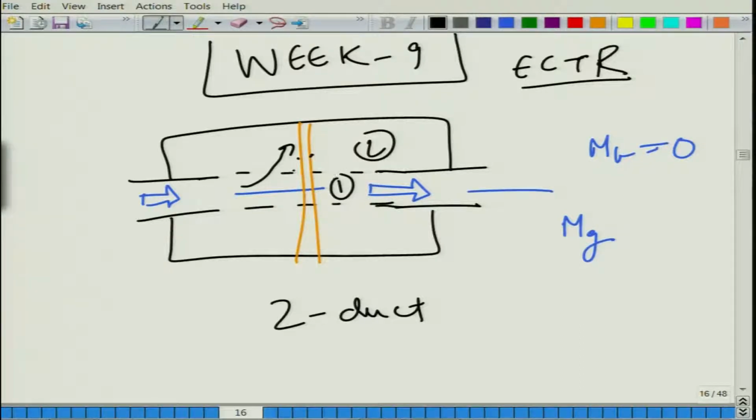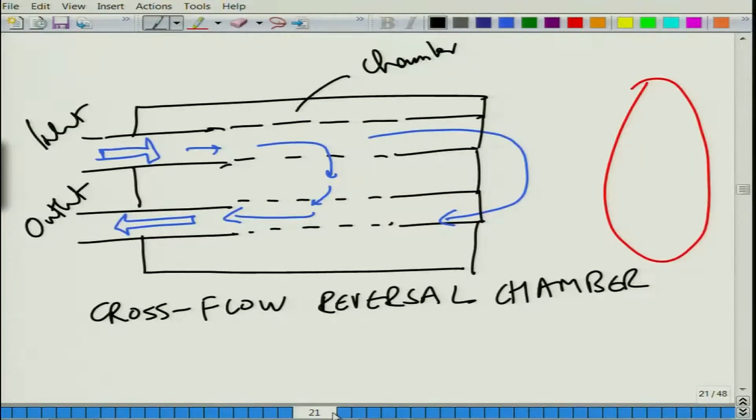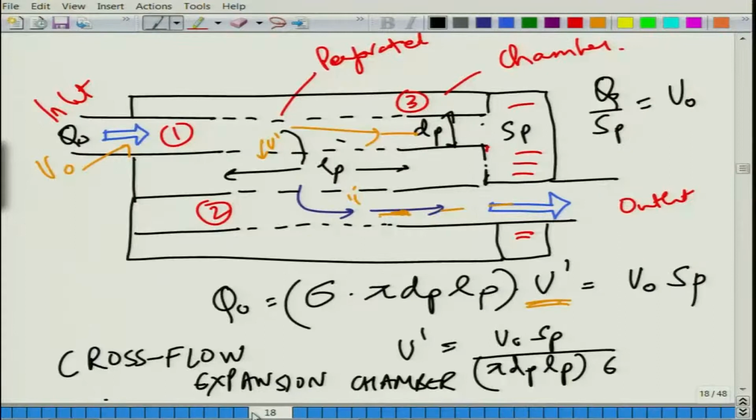It will be minimum somewhere in the middle, and then it will gradually pick up and reach a steady value. A CFD analysis would do proper justice, especially when you come to a configuration like this one or perhaps this one, where the grazing flow tends to go to almost 0 value.